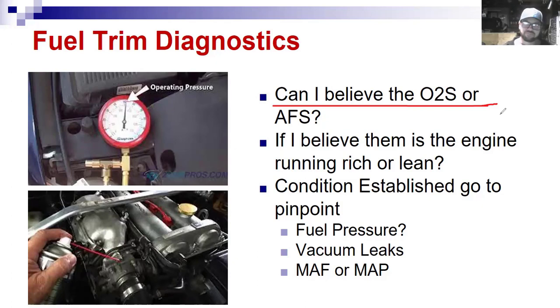I could have other problems with the engine. I could actually have a misfire due to, let's say, a bad spark plug wire or a bad coil pack. And so instead of burning the air fuel mixture in that particular cylinder, it just pumps that air down the exhaust. The O2 sensor sees that and thinks it's lean.